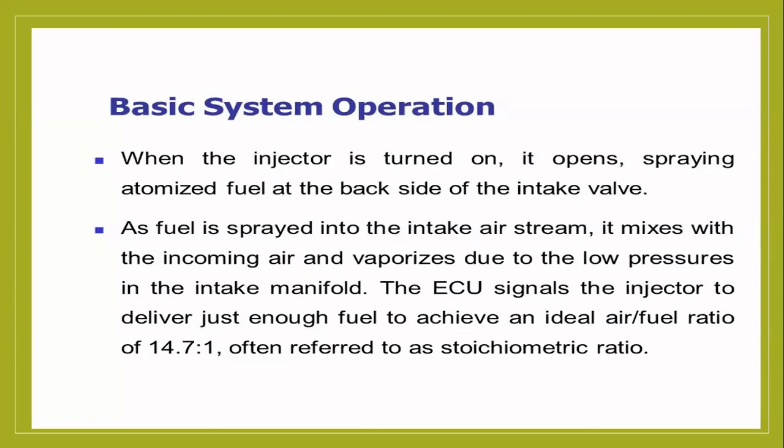Spraying atomized fuel on the side of the intake valve, right? The fuel is sprayed into the intake air stream. I told you air is compressed there. It mixes with the incoming air and vaporizes due to the low pressure in the intake manifold.